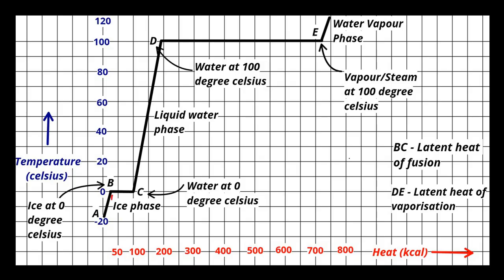But whenever there are two phases together, two states coexisting, solid-liquid, liquid-vapor, there will always be the application of latent heat at constant temperature, and that extra heat will be utilized to change the state entirely. So for different materials it will be different. I chose the simplest explanation through the simple experiment of ice, water and water vapor because it is easy to perform. So this is the concept of latent heat.